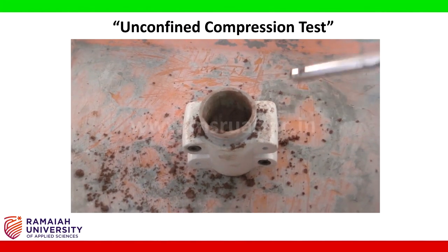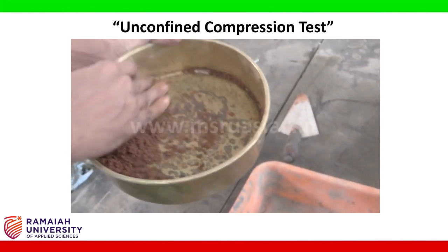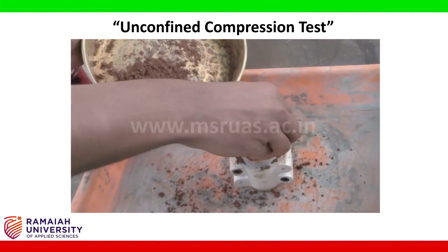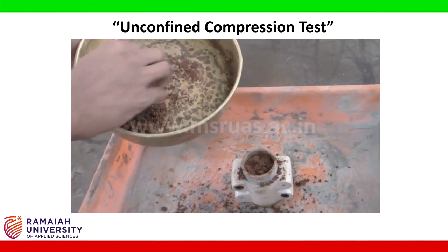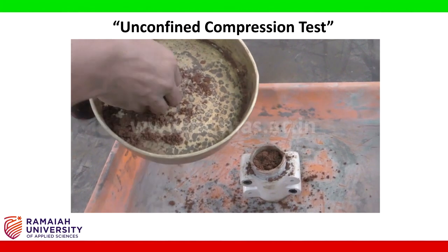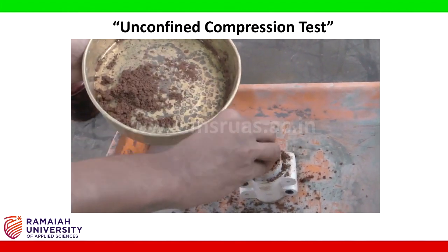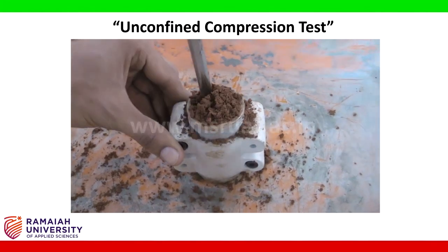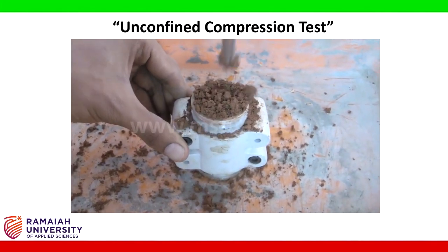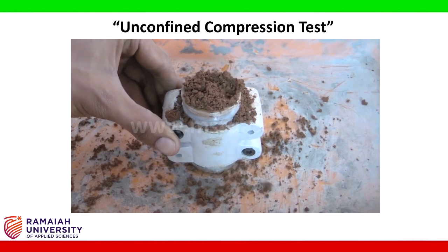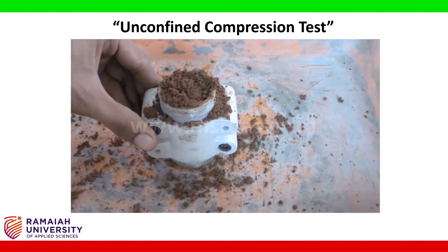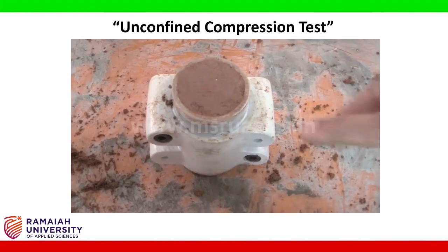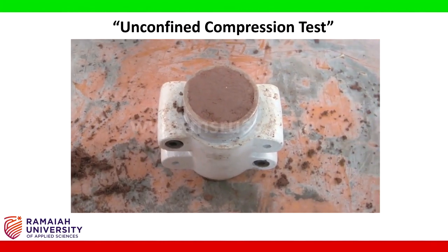After filling the second layer, now we will fill this with the last layer. After filling the top layer, we will compact it again and level the surface. Now level the top surface.